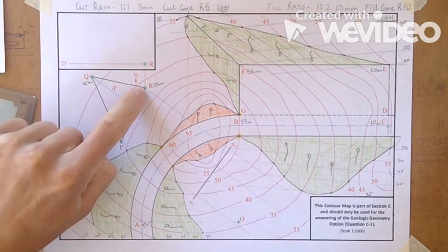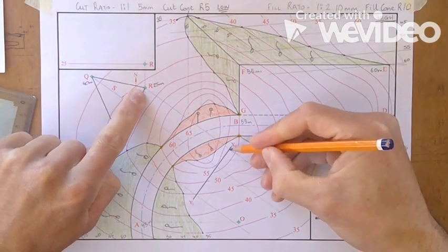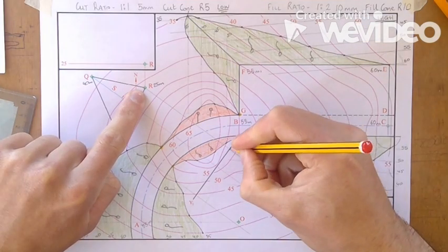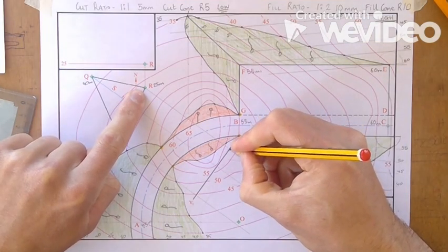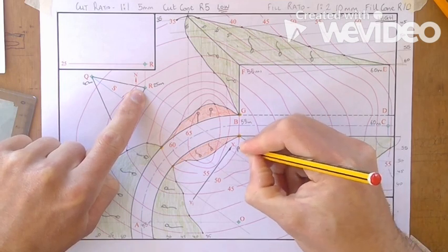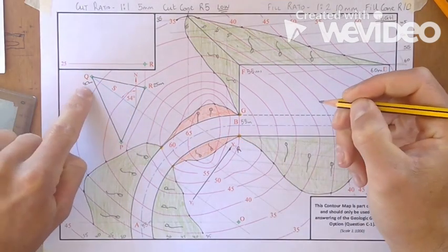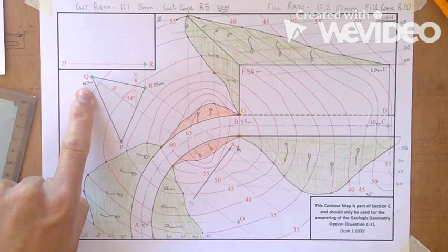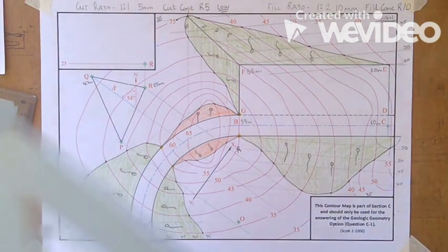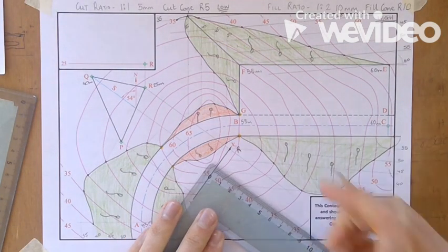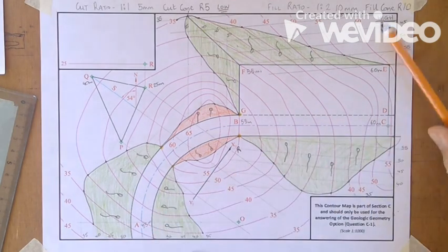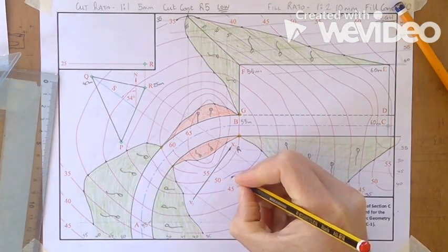Now we're going to say point R, 25 meters. We're going to put that on the X1, Y1 line. So that's going to be a datum at 25 meters. That's point R. Now from that then we need to go up another 15 to get point Q, because 25 and 15 is 40. So there's point Q.